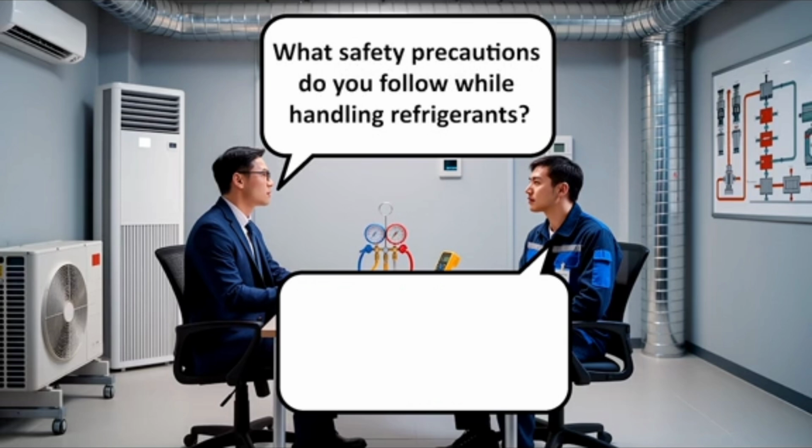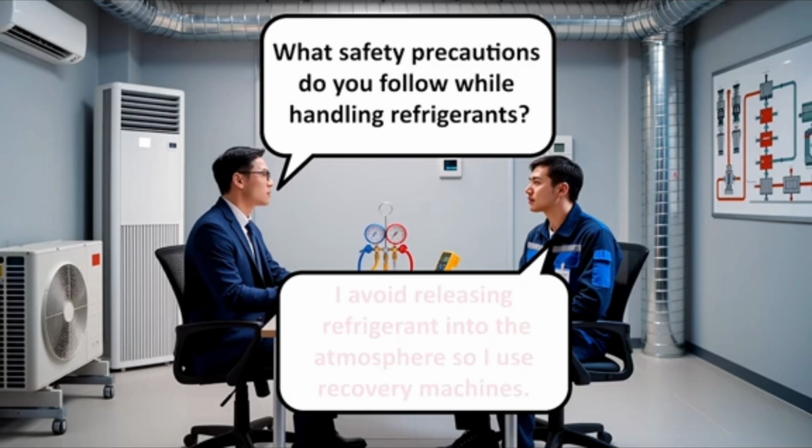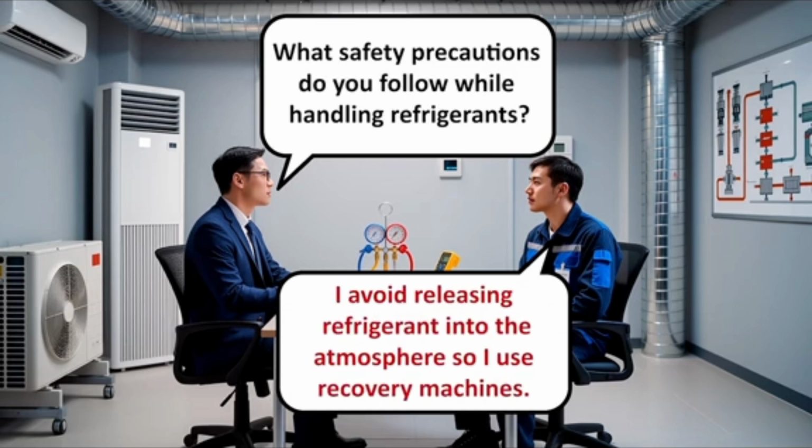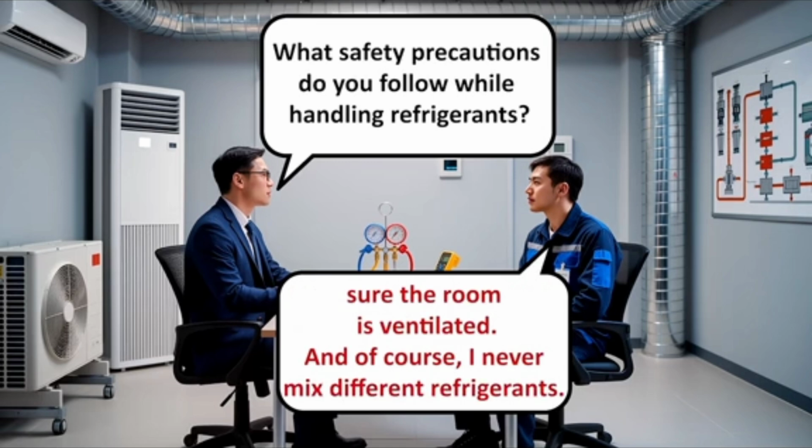What safety precautions do you follow while handling refrigerants? I always wear gloves and safety goggles. I avoid releasing refrigerant into the atmosphere, so I use recovery machines. I store cylinders upright, check for leaks with soap solution or electronic detectors, and make sure the room is ventilated. And of course, I never mix different refrigerants.